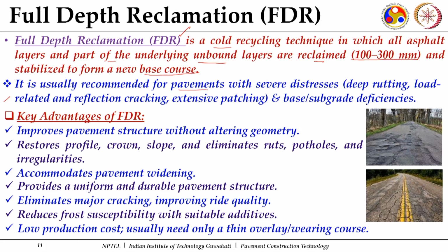It is usually recommended for pavements with severe distresses, when you have deep ruts and the lower layers are the ones contributing to these distresses. If the distress is because of your unbound courses, then deep rutting, load related cracking, reflection cracking, extensive patching. We need to go down in that case, where base and subgrade deficiencies are there. So, then you will prepare a good stabilized base course so as to strengthen your pavement structure.